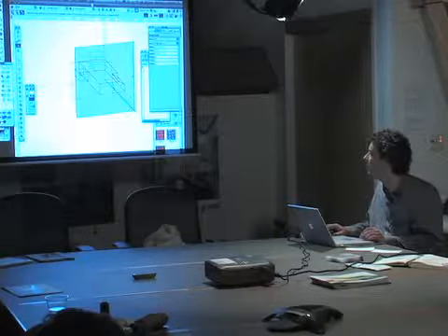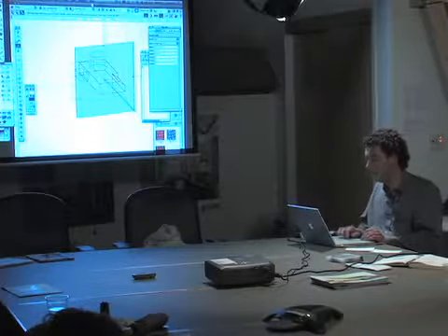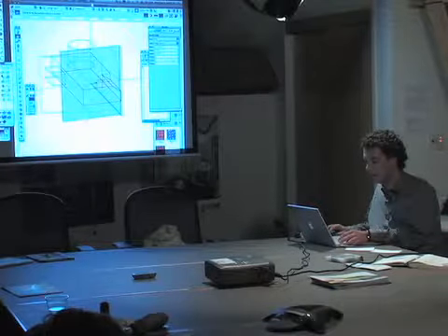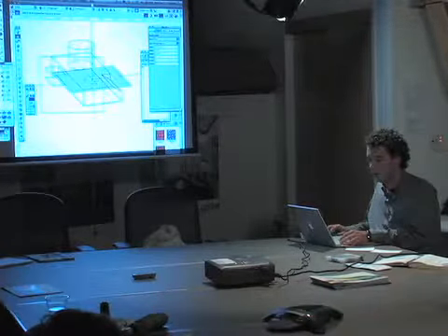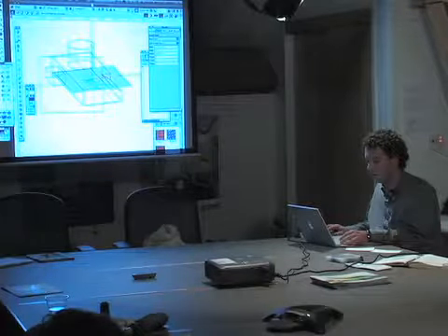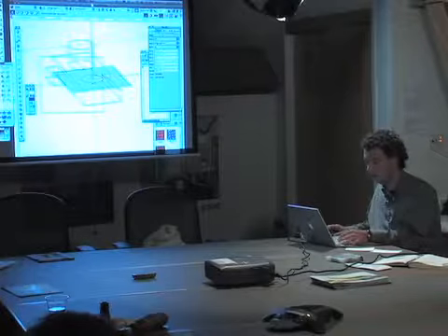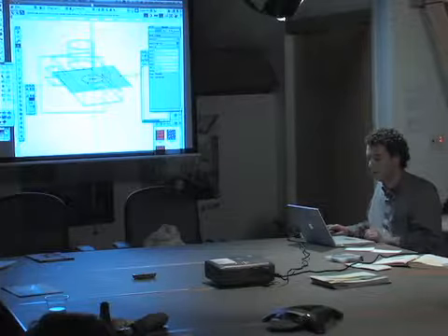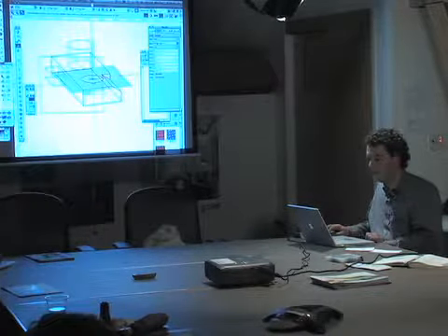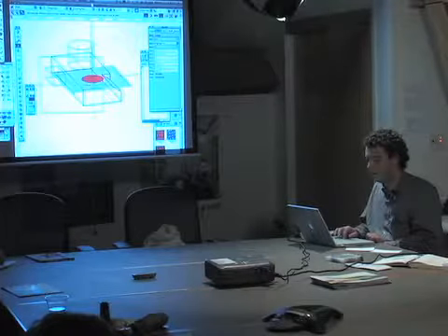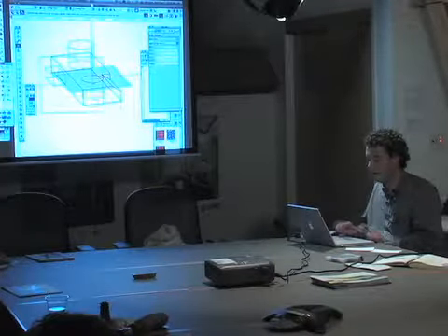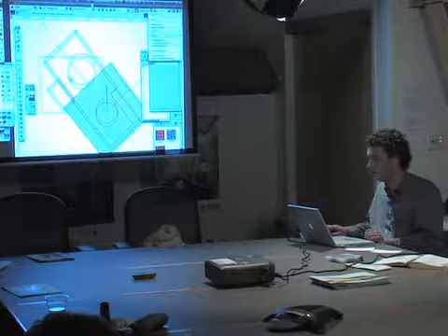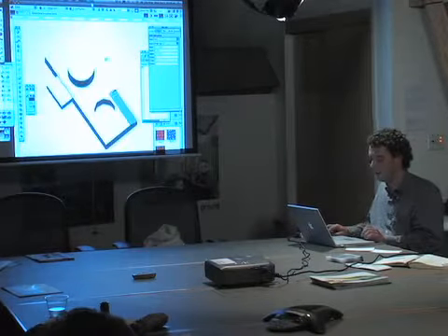So that allows me to begin to split up that face. So Shift I, let me put a circle on top. Go back to my protrusion cutout, third mode. Select the object that I want to cut away, then select the model that I want to take it away from, and that cuts that hole right in that object.